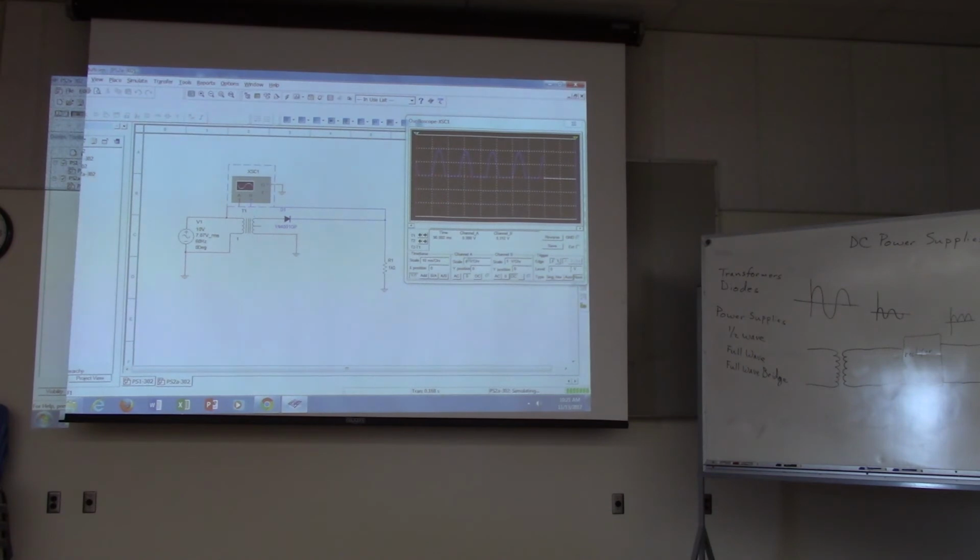The reason for that is that the input signal is on channel A and the coupling is set to 0. So that just means that it's always 0. So we'll change that to DC. Now we can see the input and the output signal, right? The input signal is in red. You can see it's going positive and negative, and then the output signal is in blue. We're capturing only the positive halves of the signal, okay?